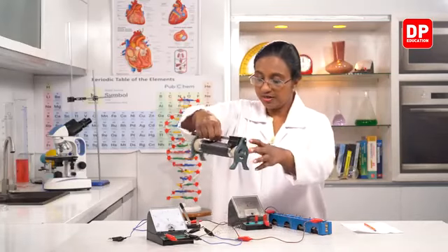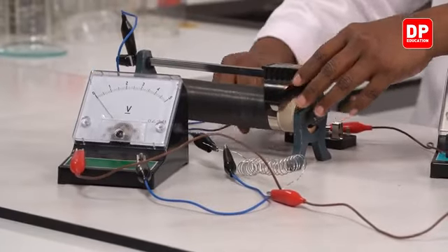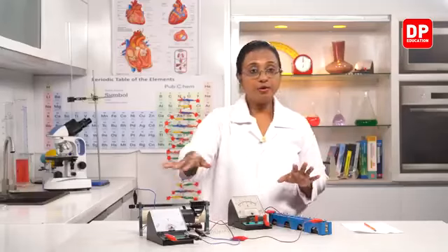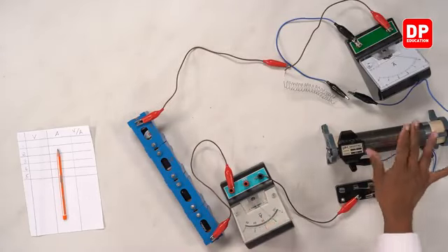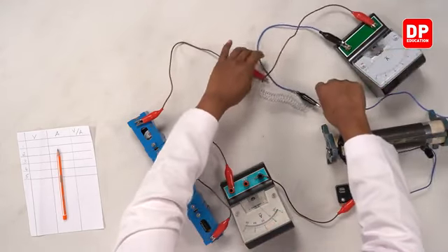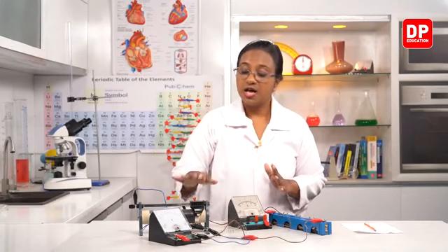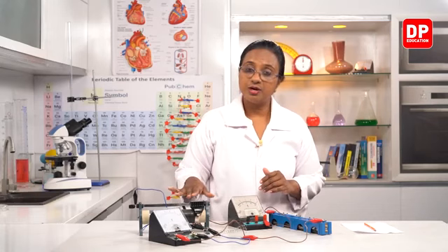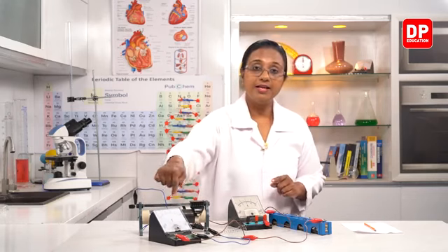So now I am going to connect it to the circuit here. I'm going to connect this terminal and this terminal. Now everything has been connected: the dry cells, ammeter, switch, rheostat, voltmeter and the nichrome coil. So every time, before I turn on the switch, I will be changing the rheostat. So different values of resistance provided by the rheostat. At that time, you have to look at the readings of the voltmeter and the ammeter. So that is how we are going to do the activity.